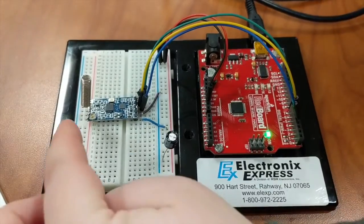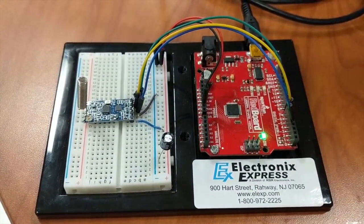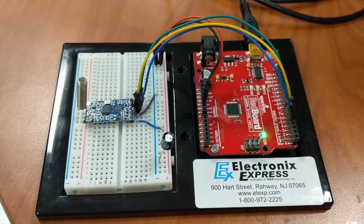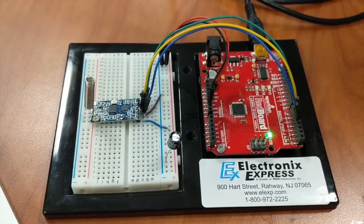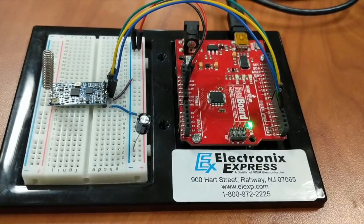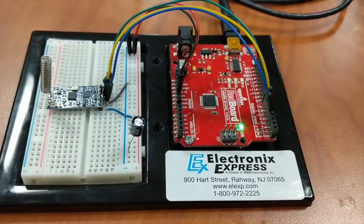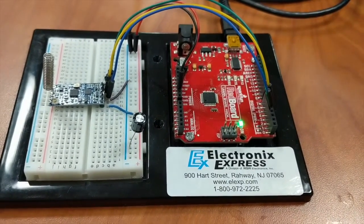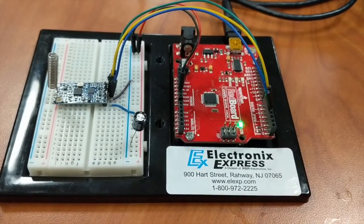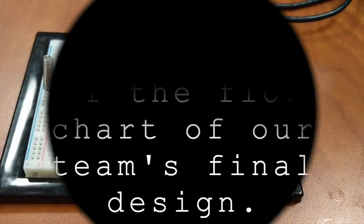Also, an antenna is soldered on the transceiver to increase our range, and a USB is plugged in to power the Arduino, which also outputs 5 volts to the transceiver. As you can see, the RX and TX LEDs and the blue LEDs are blinking. That means we're uploading the code, and if we transmit a command, the TX LED would blink again, and if we receive something, the RX LED would blink again.